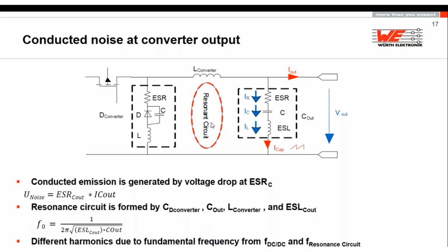How to avoid that? It's quite a simple method: use, instead of a diode, a synchronous buck where you have two MOSFETs and you emulate a diode. With this, you may have a little bit less ringing and a little bit less overshoot. But the best thing is always to keep the diode or MOSFET and the output capacitor, including the storage inductor, as short as possible. If you get this area as short as possible and you don't build big long antennas, it may be helpful as well.